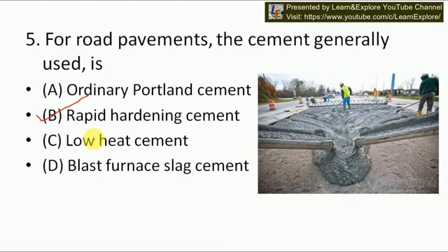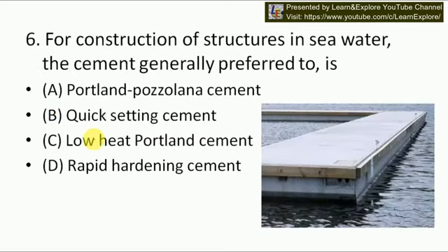Okay, so our next question is, for construction of structures in seawater, the cement generally preferred is. So what is it? Portland pozzolana cement, quick setting cement, low heat Portland cement, rapid hardening cement? Okay, so our answer is A, Portland pozzolana cement.